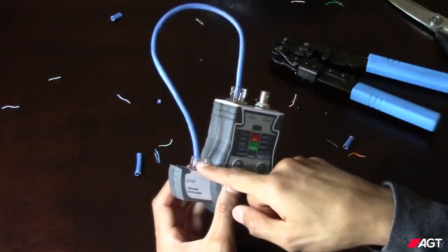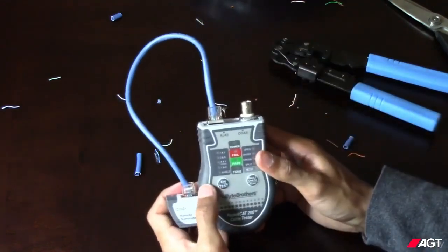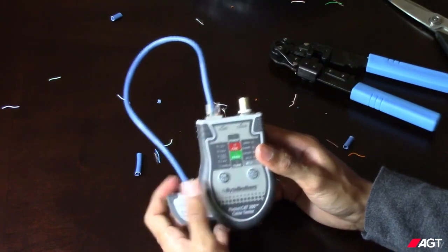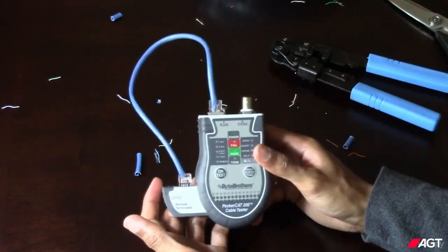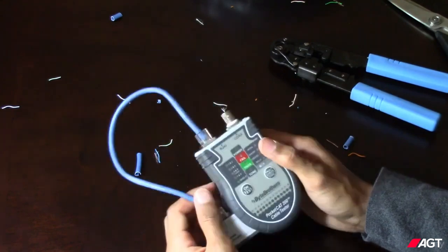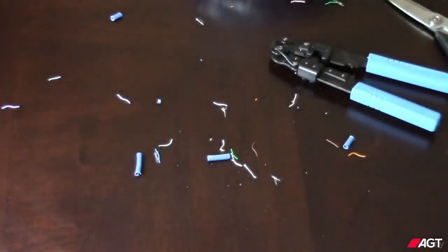This method that we use to create a patch cable is exactly what you use in order to test a new spool of cable. So if you went out and just got a 300-foot roll of Cat6 cable and started installing it without testing it first, it could be really painful to find out that it doesn't even work. So always create a patch cable and test your cable before installing them.